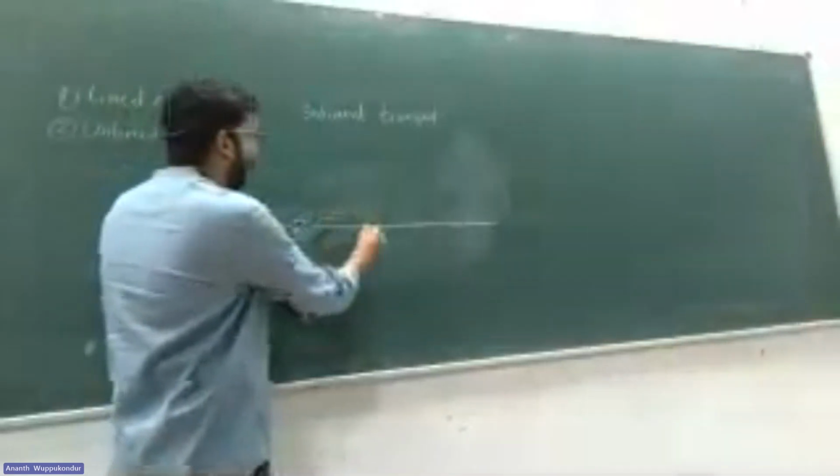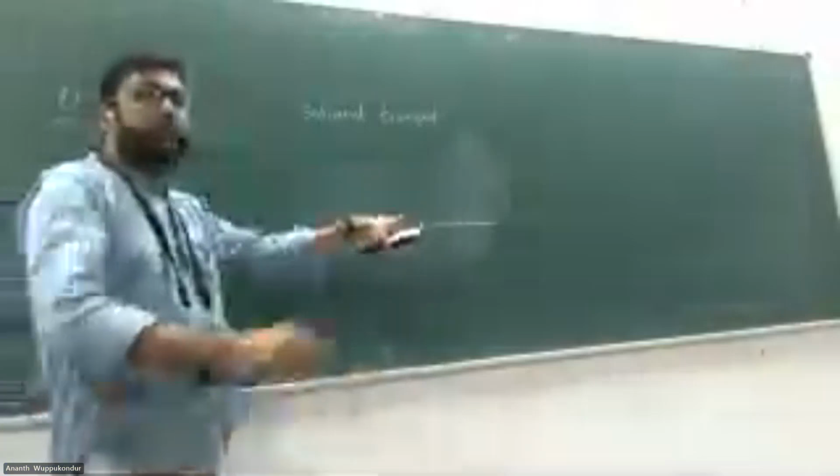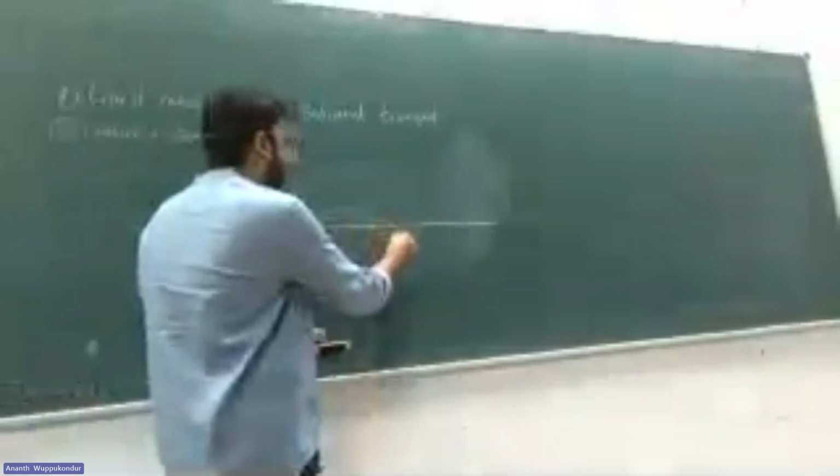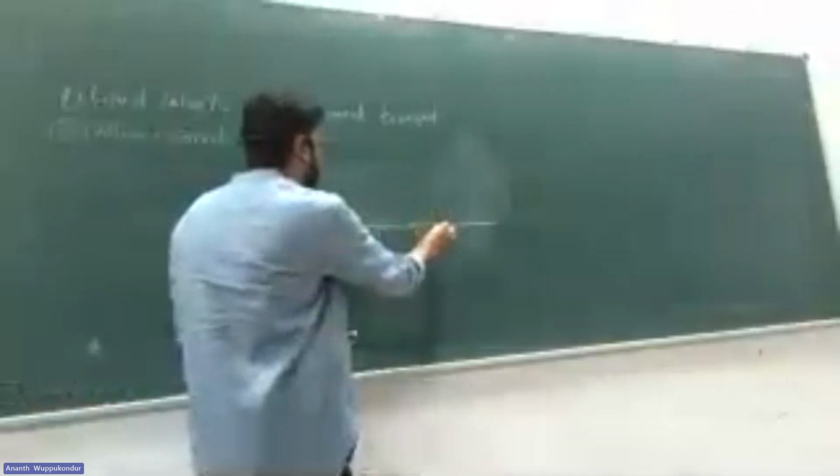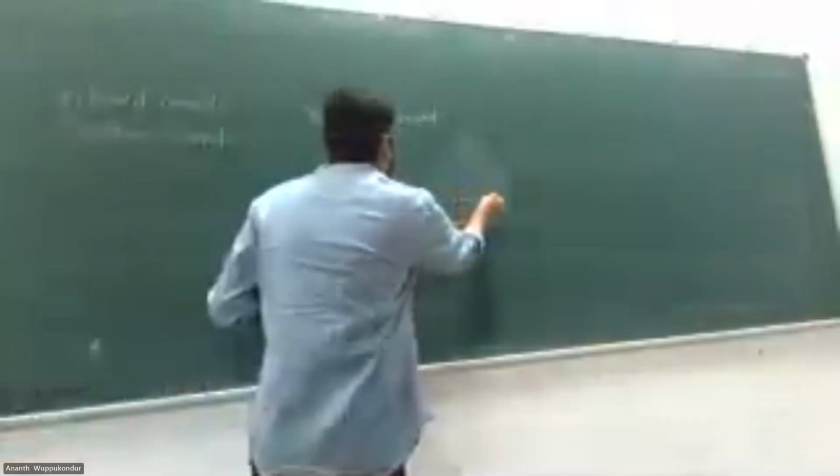So it could be jumping, or it could be just sliding, or it goes into suspension and then it comes back again. So all of this happens within the short distance from the bed. Let's say it's all happening within this distance. So this is bed load. Because the main transport mechanism is happening close to the bed.